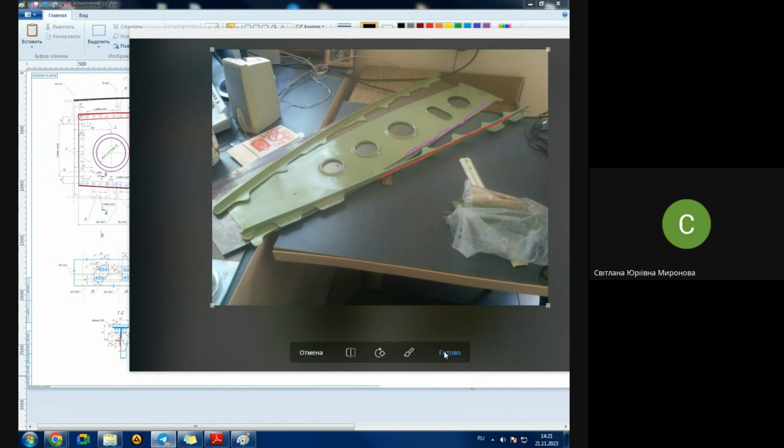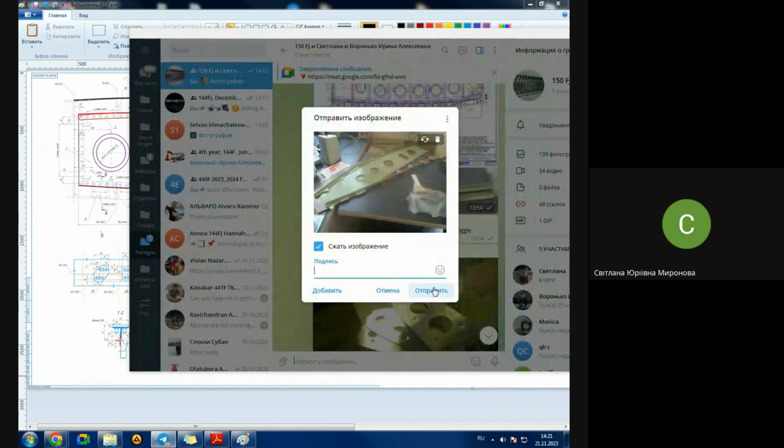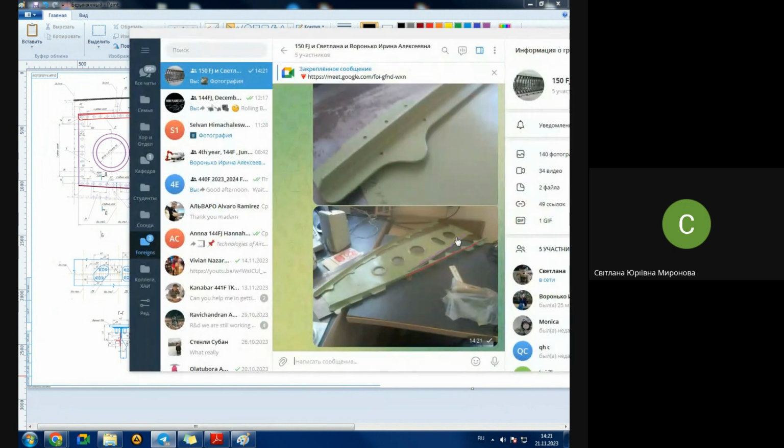What is the possible way? Either we go into measuring, which is complicated because parts are non-stiff, because this clearance is very little, and so on. It's complicated and slows down the work in a shop. In order to reduce these difficulties, in order to reduce occasional mistakes, what might we do? We might use techniques of, let's say, half automatic locating. And among them, the most simple and most convenient is assembling in a jig. Of course, a jig costs money.